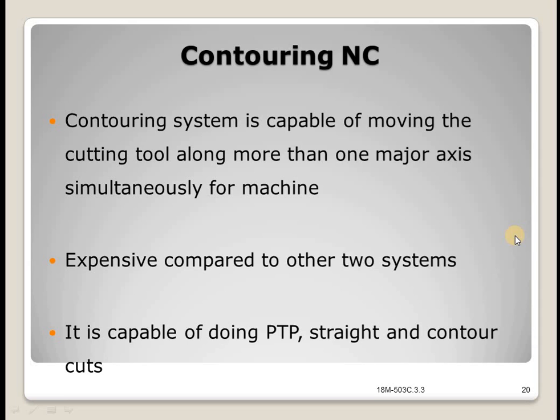Contouring systems generate a continuously controlled tool path by the capability of computing the points of the path, called interpolating. For this reason, the contouring systems are also called continuous path NC systems. All NC contouring systems have the ability to perform linear and circular or parabolic interpolation features which are recorded in the NC computer.